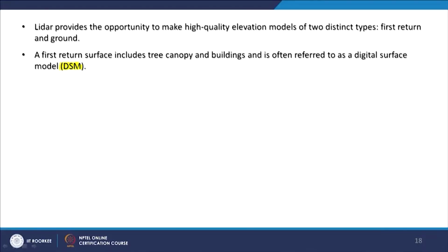As mentioned while discussing interpolations using survey topo-sheets point heights, when you have a high density of points, observations, and measurements, your digital elevation model is going to be very accurate, because this is what your interpolation techniques require. In the LIDAR technique, as you know, it first generates the DSM, the digital surface model, which we have discussed in earlier lectures. So, not directly a digital elevation model.